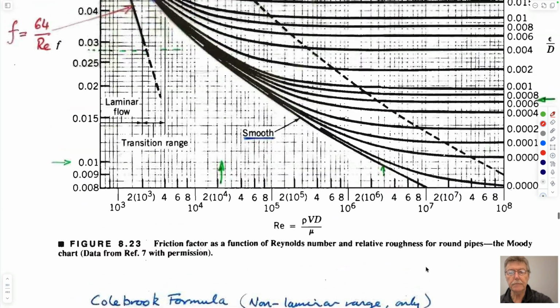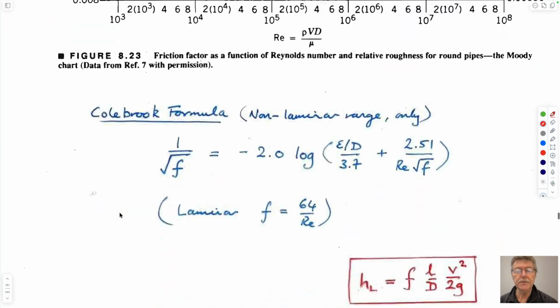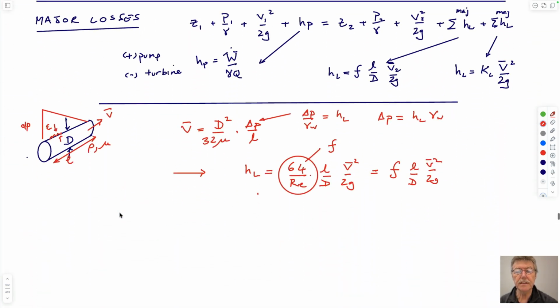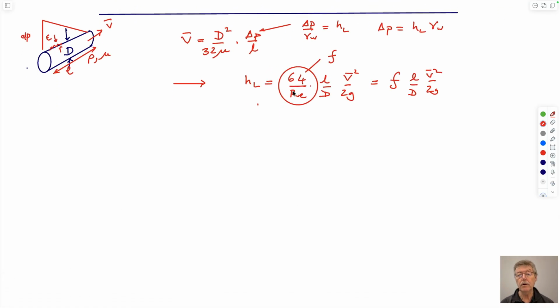And so I'll come back down here in a second. This is exactly what we would get if we plotted Euler number versus Reynolds number for doing the experiments in a pipe by just jacking up the pressure in a single pipe and measuring the change in flow rates out of the system. We kind of did it last time. And so this is true for laminar flow only. And that would make our, what do I want to draw? I'm going to draw the Moody chart just by hand, just because I can introduce the most important features.